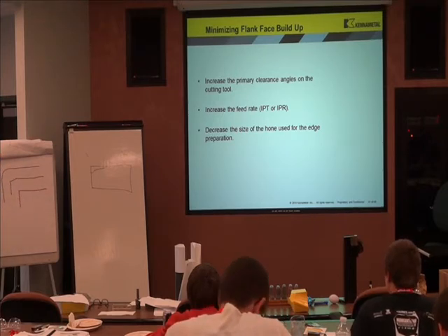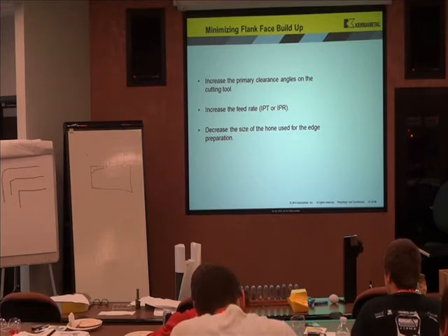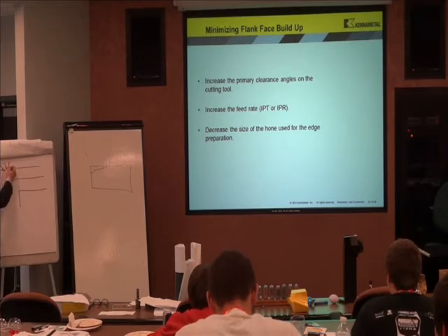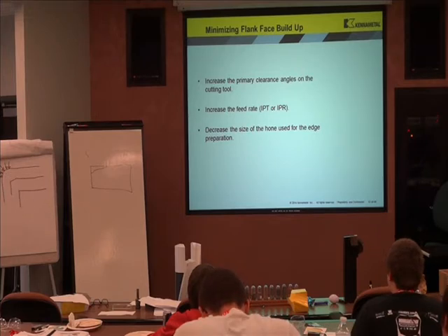The one thing I know, cutting forces are always what to the cutting edge? Perpendicular. When I have this big radius, I have an infinite number of perpendiculars. All my cutting forces are going into the compressive strength of my tool. Make sense? That's why I put it.